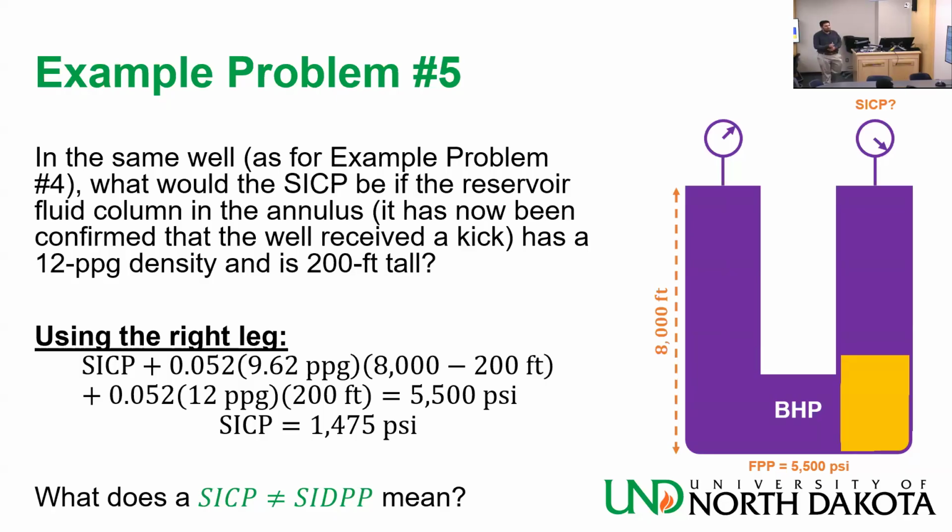So it's basically to make your mind understand that I can have gas, which is a very light, very low density fluid, at a very high pressure, and get a gas kick. In fact, gas kicks are very, very dangerous. Why is it dangerous? Because then that gas, very low density in something very high density, is moving up like a balloon. So it's bringing pressure from the reservoir up to the surface. You shut the well, but it's still moving, creeping up, so you have to make decisions fast.